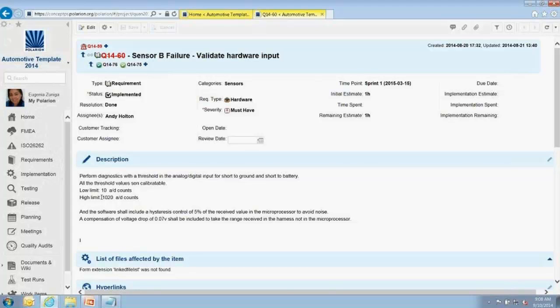And then on the release, this is the last part that I'm going to explain before going to questions. In here we have the official release, which is pretty much what you're going to deliver to the customer. It's like, okay, I want to know what you're delivering. I want to know the content. So yep, you have your traceability information, content, your hex files, your RAM usage, ROM calibrations, your part numbers, and then you have the features that were requested, the requirements affected, the bug fixes, the calibration tasks, anything that is assigned to somebody else outside of your company, the test results, the quality results.